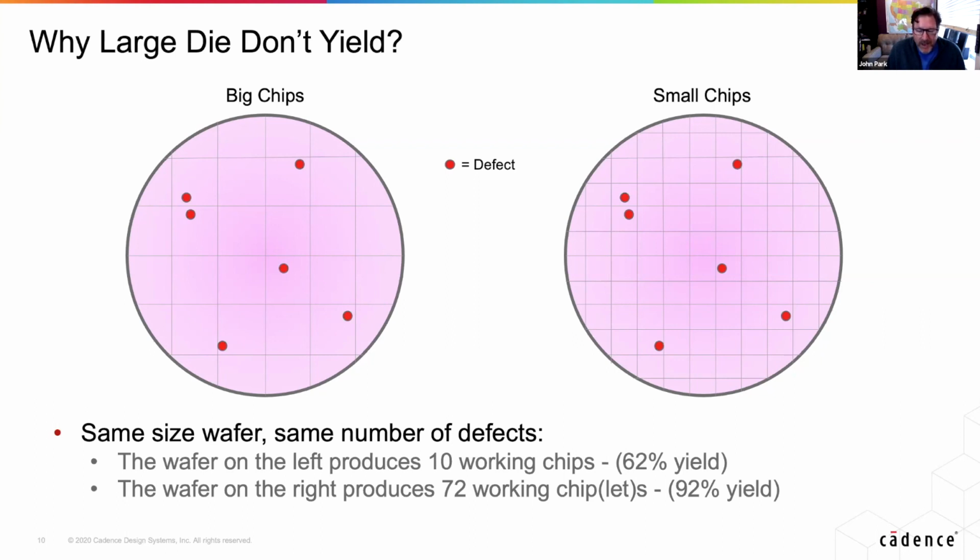They get thrown out, and that increases the cost of your chip. The more chips you throw out, the more wafers I have to make to get good chips. That's where the cost factor comes in. So having really low yield on a wafer just increases the cost exponentially and gets out of hand.